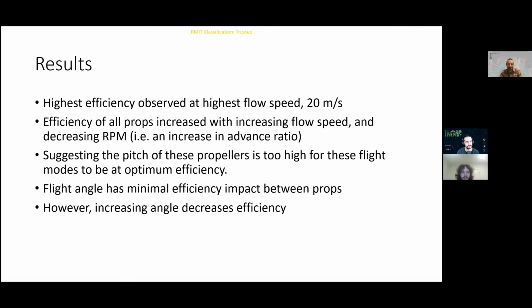And there I found a lot flexed very significantly at high RPM. And if you looked at them side on in the blade plane, you could see the tips bending really significantly forwards. Those ones suffered quite a lot. So at higher RPM, they had big efficiency decreases.